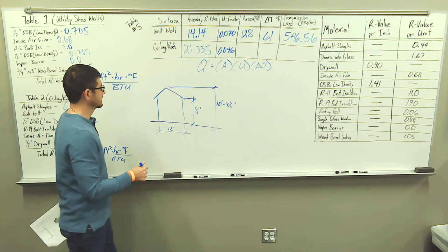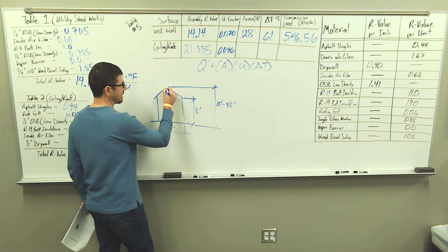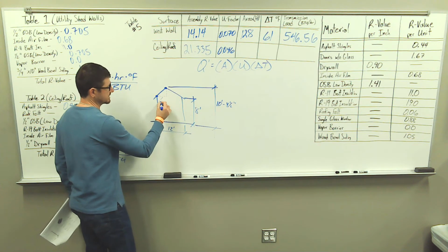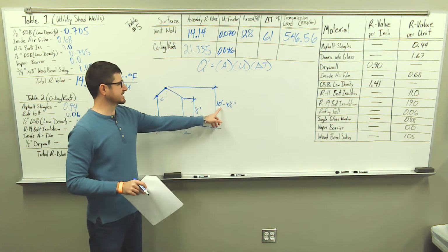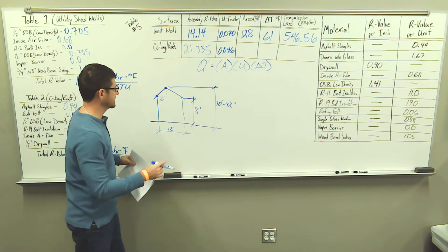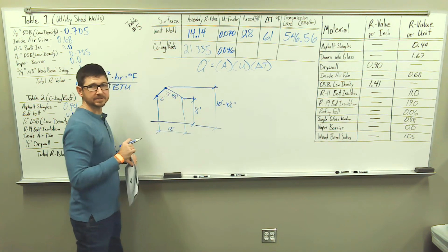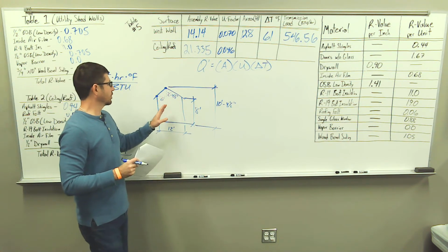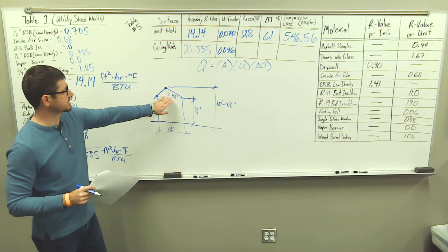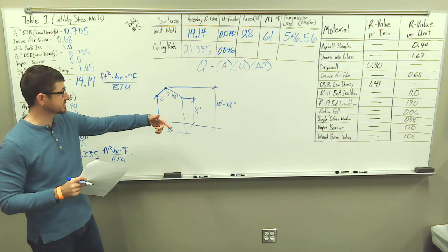width of our shed. So what we're going to have to do is calculate our hypotenuse value here. So we have 6 foot here, and if this is 10 foot, 4.5 inches, and this is 8 foot, that means this is 2 foot, 4.5 inches. Now, what we need to do is convert these values into inches, because this is going to be a weird decimal value that's going to be hard to convert back to inches later on.